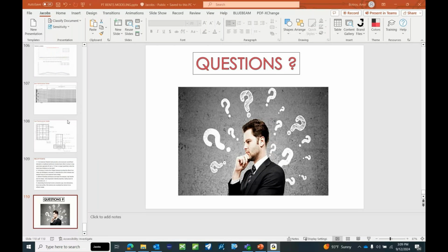The way that this load is actually transferred from the vehicle or from the moving load all the way to the superstructure or the deck and then to the substructure all goes back to the engineer, how he models it. Some people like to distribute the braking forces on the girders or on the deck right away and apply a concentrated torsion or concentrated torque on the bend. That's basically calculated by multiplying the force by the lever arm measured from the point of application of the force all the way to the centroid of the bend. So you can apply this concentrated moment and still distribute the loads on all the girders.